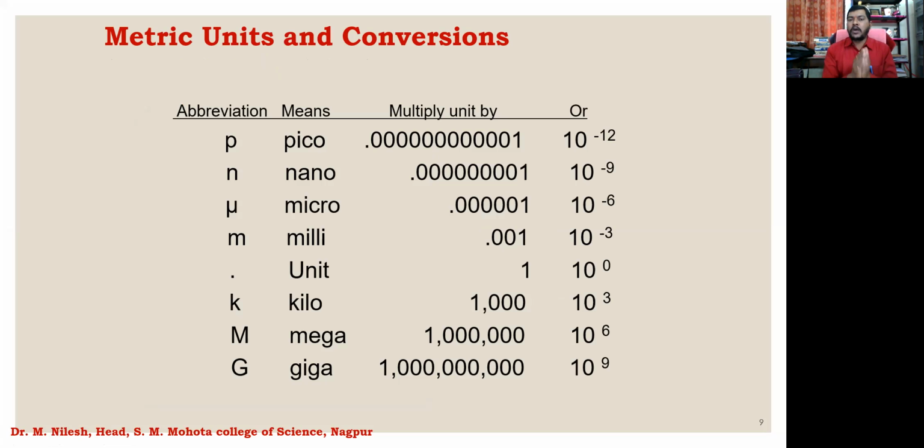And that is how I could say that the total resistance of that particular color code was equal to 4.7 kilo ohms, right? Now what kilo ohms means is 10 raised to power 3. So whenever you have this digit, that is 10 raised to power 3, or whenever it is written as a small k, you have to understand that it is being multiplied by 10 raised to power 3.